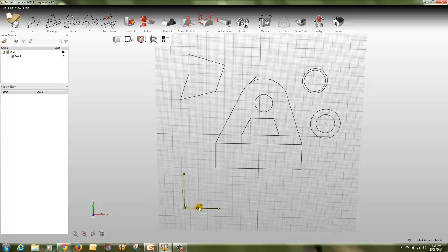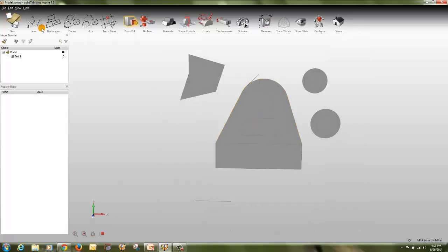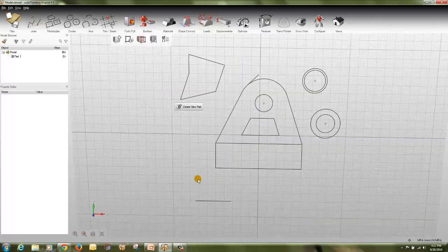Select both the lines, control left click, parallel. So they will become parallel. So you can now move one line. If you click on one, make your mouse in one, so you can see the parallel constraint symbol is there. The double line, parallel constraints symbol is there. So in this way you can create parallel constraints. You can also make this line horizontal to vertical. So both the lines will go to vertical or horizontal. So in this way you can edit these changes.